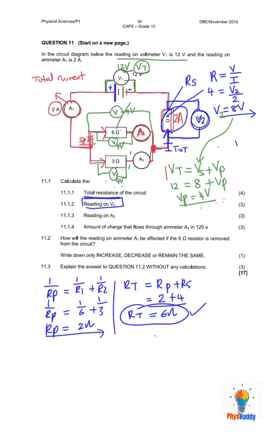So from the total, some of the voltage goes to series and some of the voltage goes to parallel. So if my total was 12 and 8 goes to series, that left us with a parallel voltage of 4 volts. And now it would be easy for me to find the reading on ammeter A2. Ammeter A2 measures the current in the 6 ohm resistor.